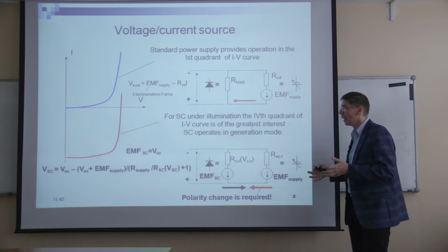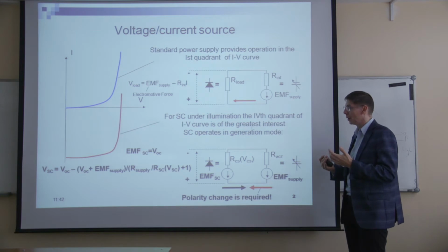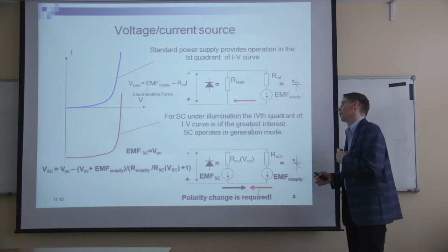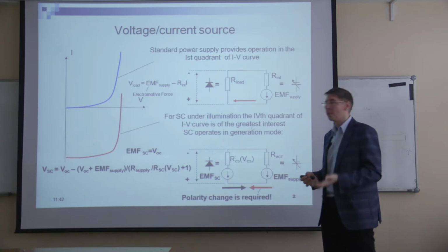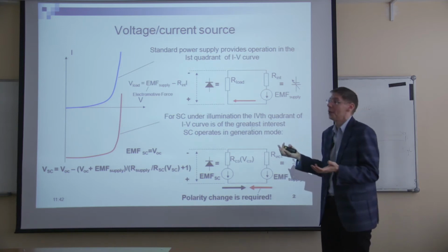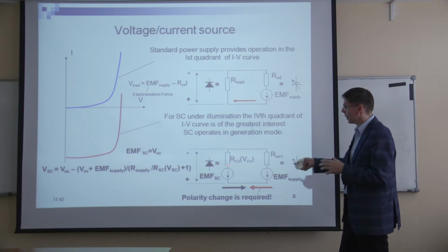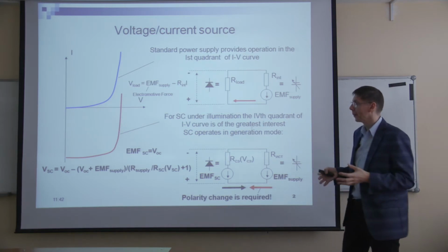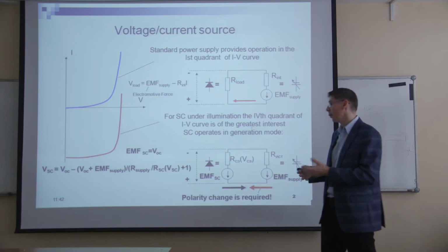Concerning the solar cell, actually it corresponds mainly not to the efficiency, because the difference in efficiency is only a few times in magnitude. If you have a bad solar cell with 5% efficiency and a very nice solar cell with 25% efficiency, it's only a factor of 5. But this internal resistance corresponds mainly to the difference in the area of the solar cell, because the area you can scale in a few orders of magnitude.